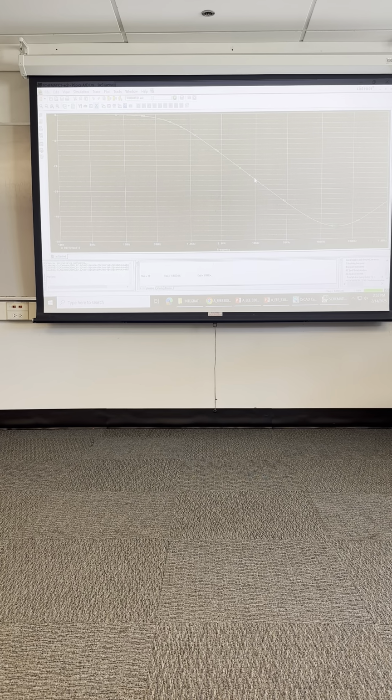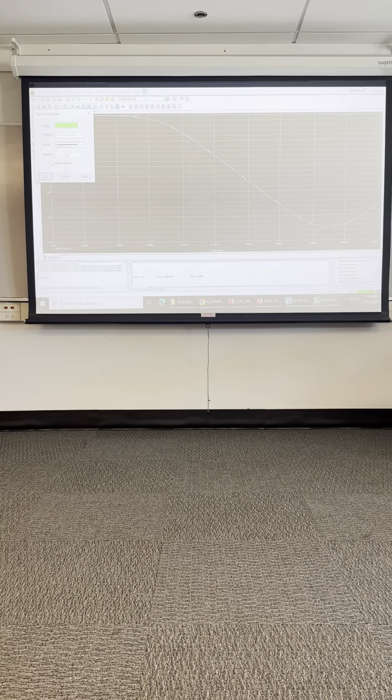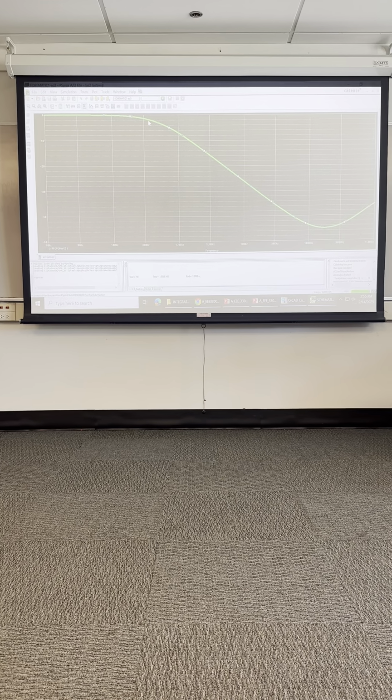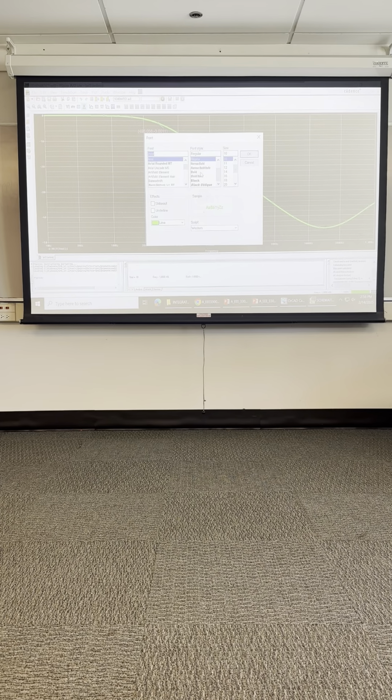And then once you get your plot with your cutoff frequency, this is one of the plots you'll need, and you'll go to plot and find the minus 3 dB. We're somewhere down here, and that's approximately minus 3 dB right there. We'll put it on your plot, make sure it's readable. So the minus 3 dB point of this circuit is 496 hertz. You can put it in kilohertz, and that's one of the plots you'll be needing.